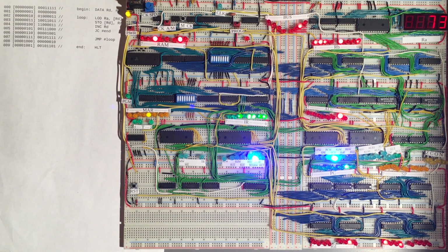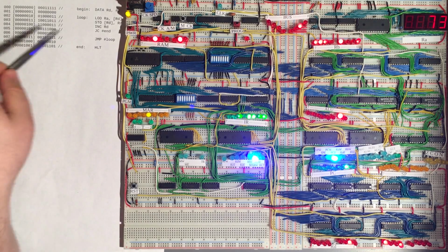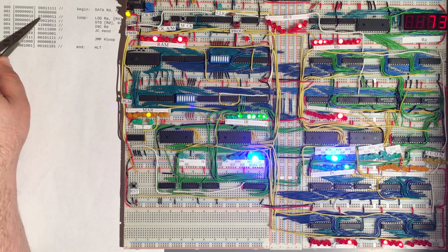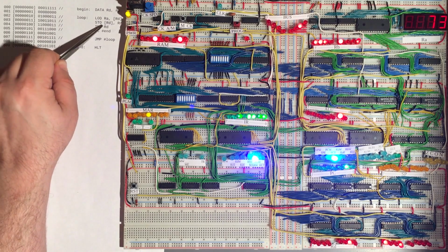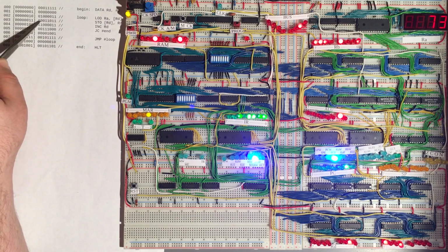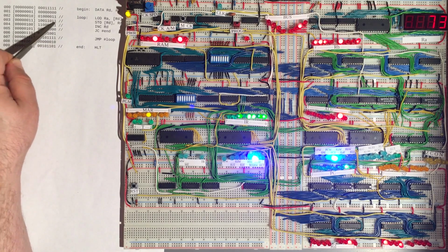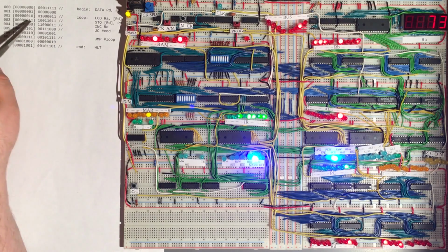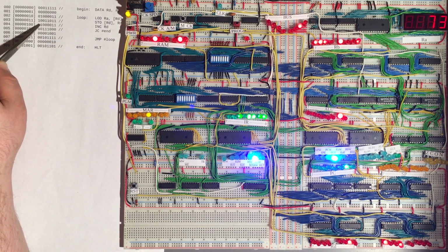Now in this episode we're going to look at the microcode for the rest of the instructions that our CPU supports. And so we divided those into the three remaining classes. Broadly, we have the load class of instructions, and so they have 0, 1 in their first two bits of the opcode. We have store class instructions, and so they have 1, 0 in the first two bits of the opcode. And then we have ALU class instructions, such as this increase instruction, and they have 1, 1 as the first two bits in their opcode.